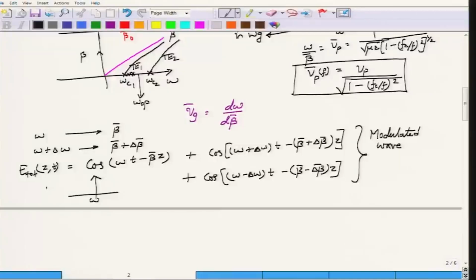When you have this situation, then there are side bands omega plus delta omega and omega minus delta omega, and the corresponding time domain waveform would be different, right. So, now you will have, in addition to the carrier, an envelope. You have this carrier and there is a corresponding envelope, and it is this envelope which is changing that conveys information to you. In a more general case, the spread will not be like this sinusoidal one, but we will not consider that at this point.